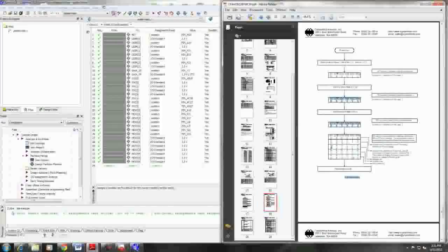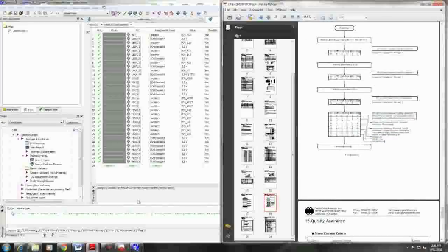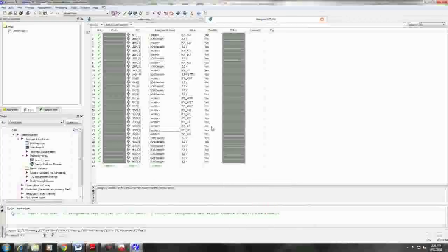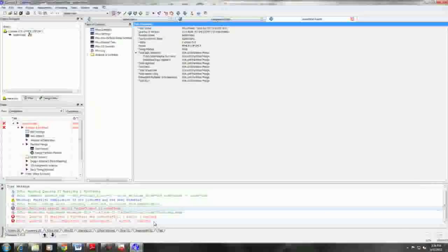And just to note something that we came across as we were building this: the sequence does not say to turn on the display, but you do need to do it, as your intuition probably already told you. Just make sure to include that in your initialization sequence. So now that we've magically gotten our pin assignments and a little gnome magically created all of our code for us, we are ready to compile our design.